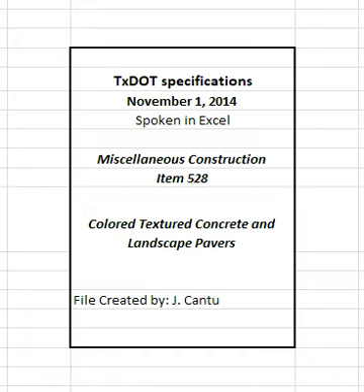3.2.3 Bedding sand installation. Screed a layer of uncompacted sand to a depth of 1 to 1.5 inches over the compacted base. Do not use bedding sand for leveling. Maintain the spread sand in a loose condition and protect against pre-compaction before and after screeding. Protect screeded sand against accidental pre-compaction, including compaction by rain or dew.